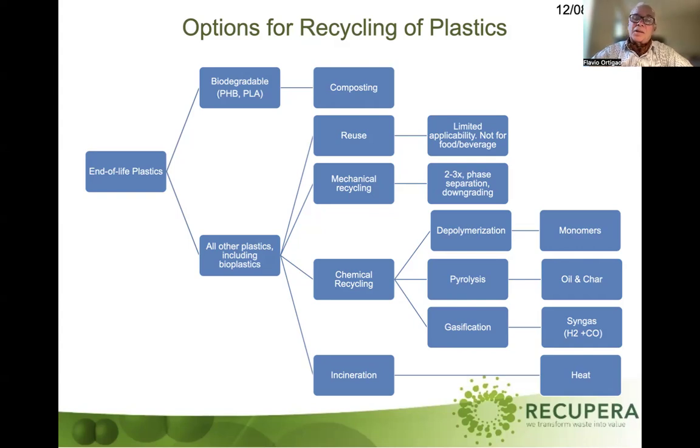Yes, chemical recycling works. There are two major technologies for chemical recycling. One is pyrolysis, which is an anoxic, thermal breakdown of the polymers. When you break down the polymers, you don't break them down to the monomers. You break the polymers statistically. Statistically means that all the possible forms, in a normal distribution, will be in the soup. There is not a single product.